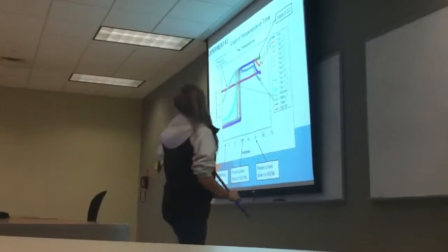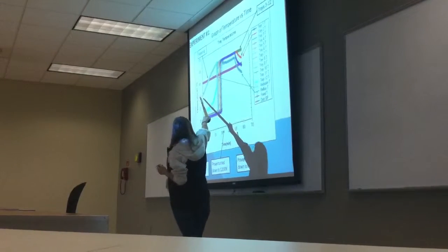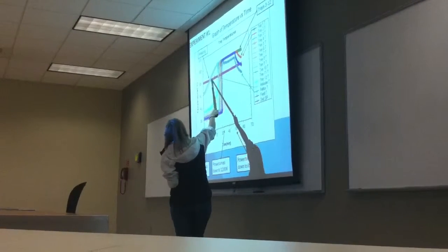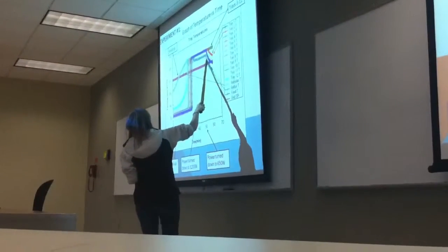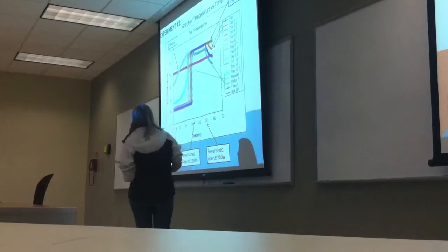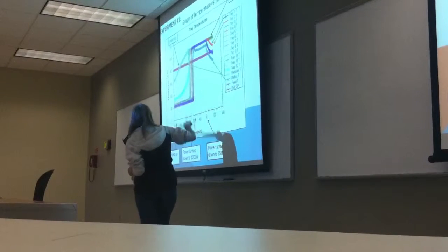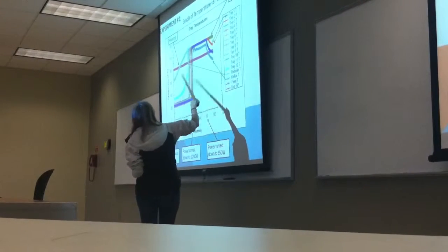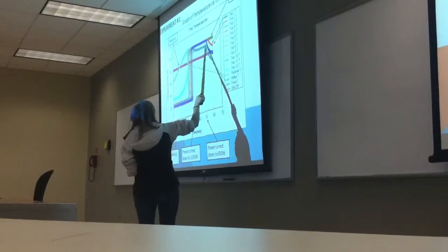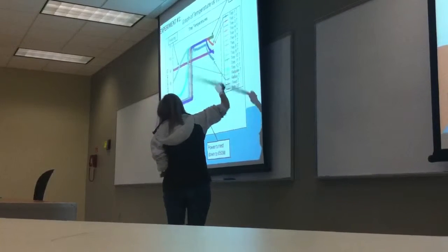Again, this is another graph that is produced with the results. So on this side, we have the heating curve, so you can see the reboiler, where it was heated up. And then this side is where it started to cool down, where we decreased the reboiler settings. So you can see here power turned up to 2400, where it started to increase. And then we turned it down from 1200. So you can see that some of them are slowly decreasing, but not all of the trays. And this is where we turned it down to 650.